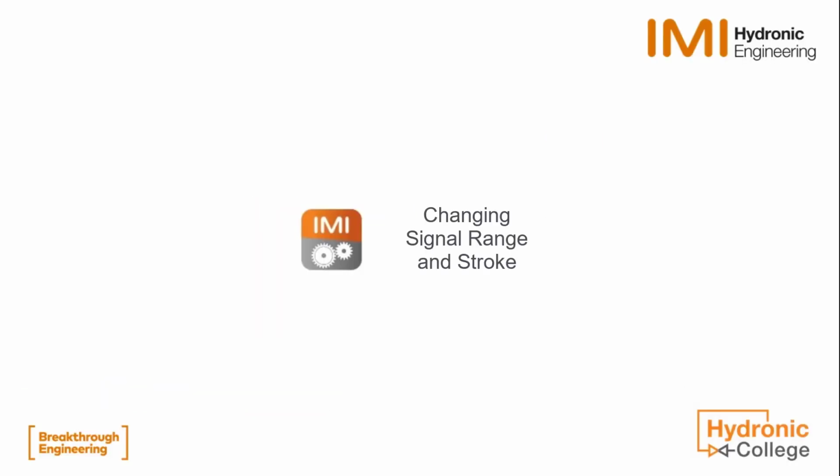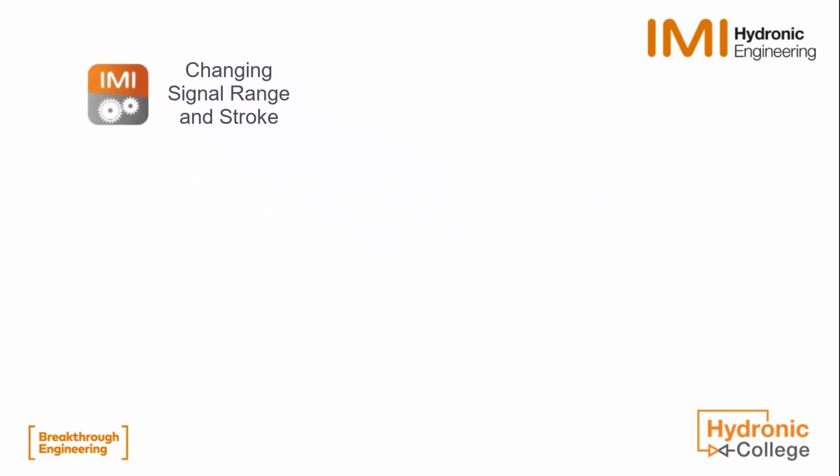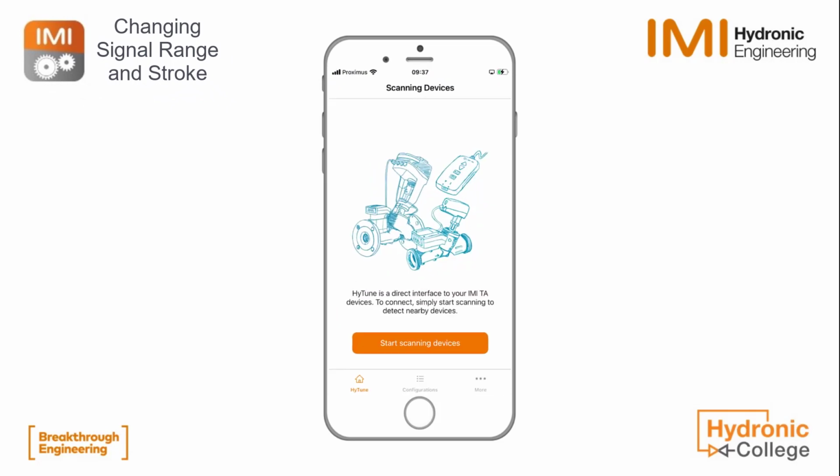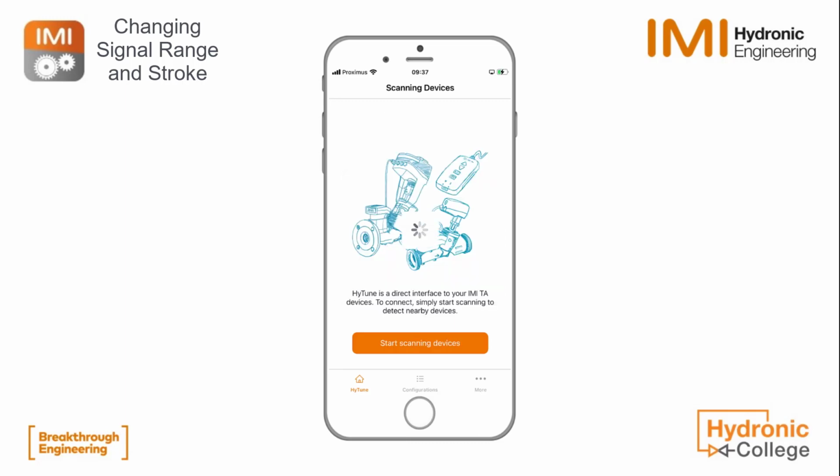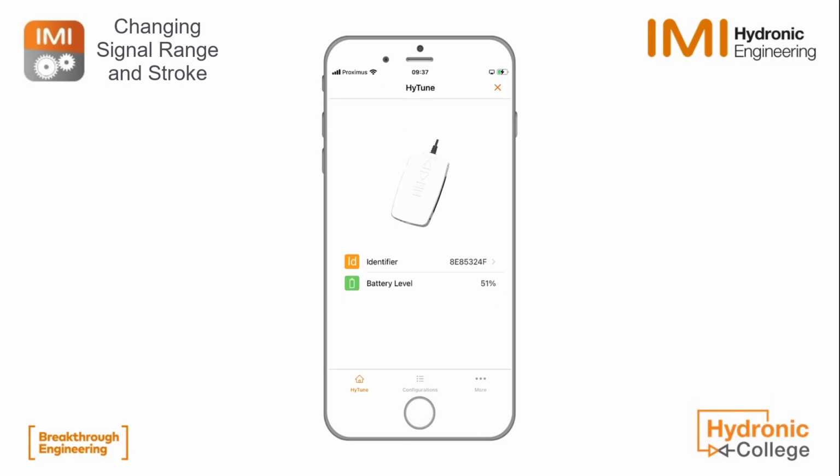In this video we learn how to change the input signal range and how to set the maximum and minimum stroke. We start by connecting to the TA slider via TA dongle and HyTune, of course. And in this case we are connected to TA slider 160 changeover.